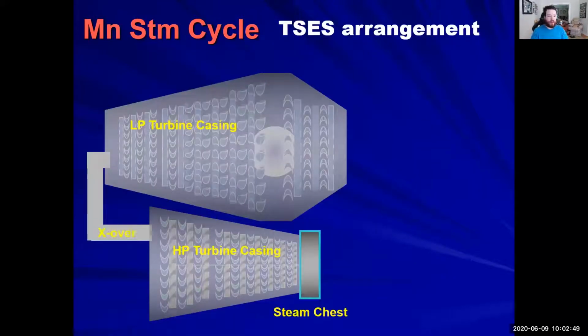And this is what we're really looking at here. We have something called a steam chest right here. That steam chest is what you would think of like we talked about a sea chest. That is where all of your steam that's going to be entering your HP turbine is flooding that steam chest, so it is going to be full of all the steam.